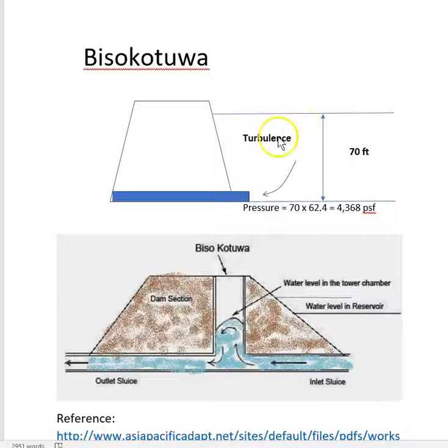And when you try to take water out of this sluice here, what's going to happen is there's going to be a lot of turbulence here. A lot of turbulence. The water is trying to gush out from here. And in the process, due to this turbulence, this bund is going to get blasted away. And these reservoirs are very dangerous in the sense that if they get blasted away, the villages downstream are going to go under and people are going to die.